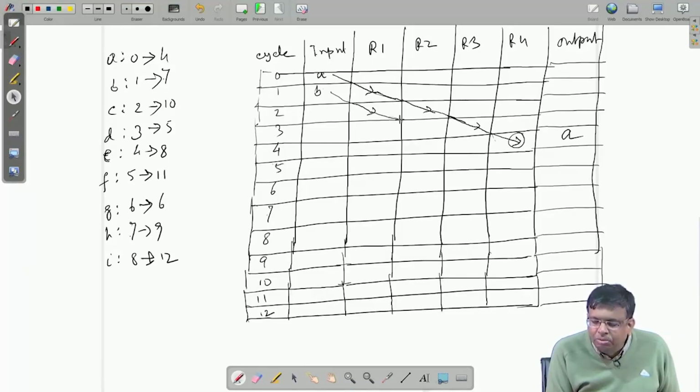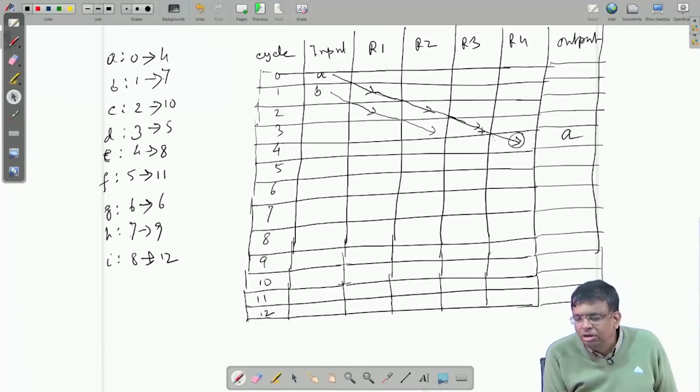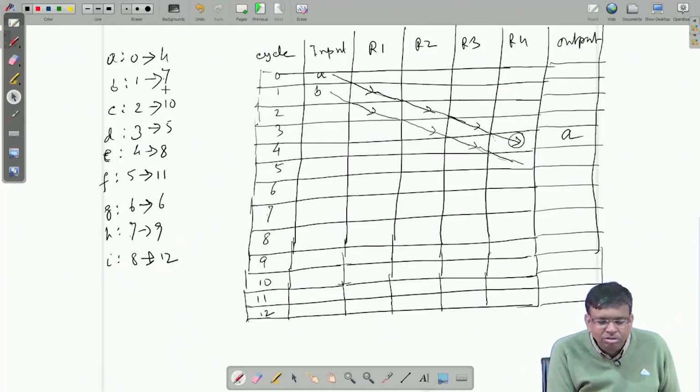Okay. B is given to the input of R2, R2 shows it at the output here at the end of cycle 3, at the end of cycle 3 R3 output shows A. So, again no conflict. Then R3, as I told you earlier, this output goes to R4 input, R4 stores it in cycle 4, and in cycle 4 R3 stores it, it goes to the output of R3. Then it goes to R4, R4 had stored A in cycle 4, in cycle 5 it is free, so it is just happily taking it from R3, storing it, but I have to go beyond.